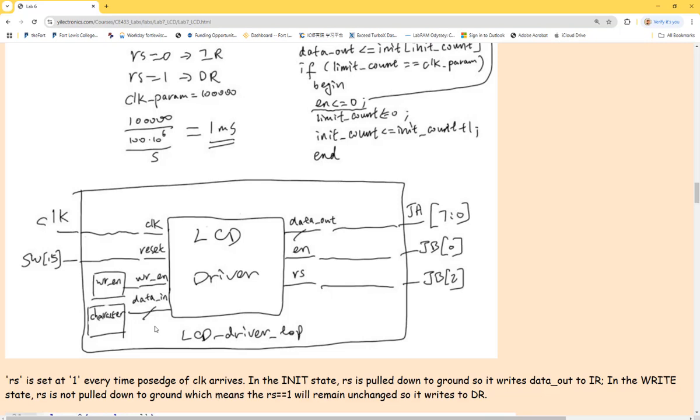The data. There isn't a microcontroller communicating with it, right? So all the inputs are from the internal logic you write into the FPGA. These are just the ASCII codes, like bytes. You assign them to regs, the register data type variables.